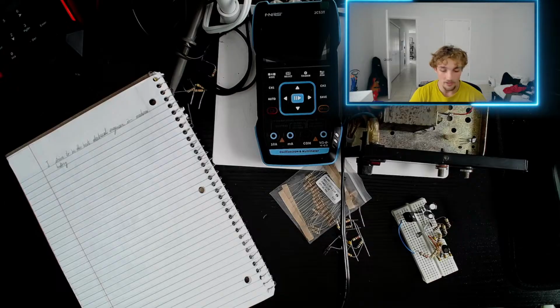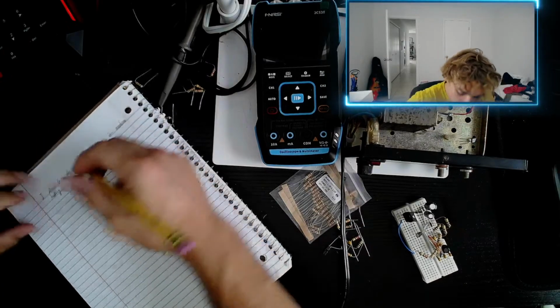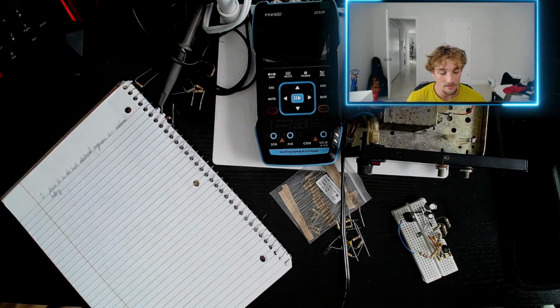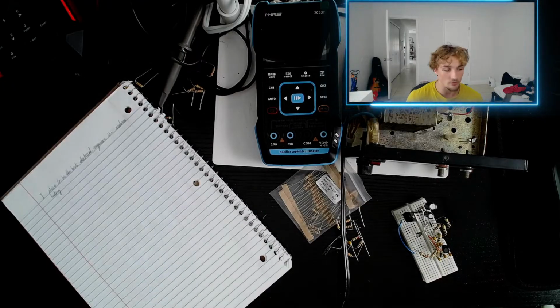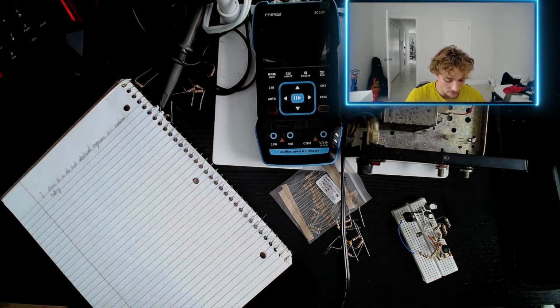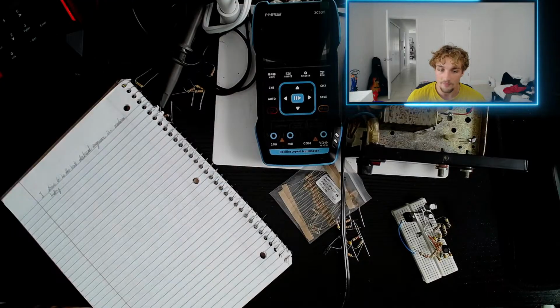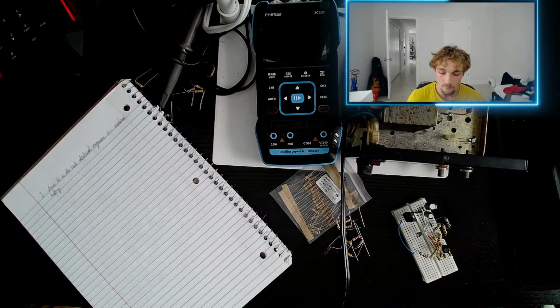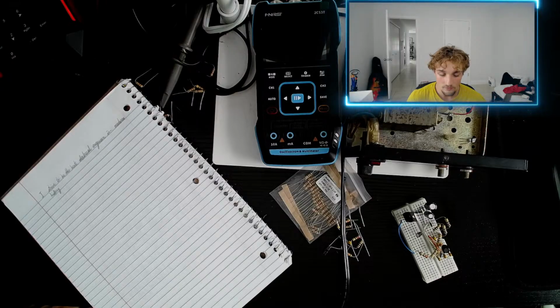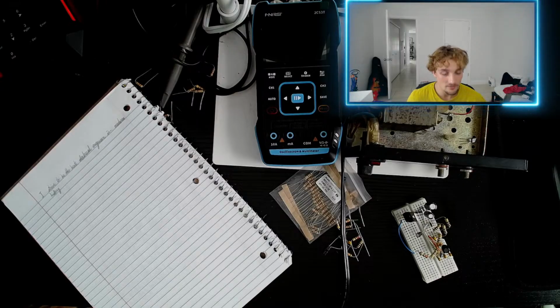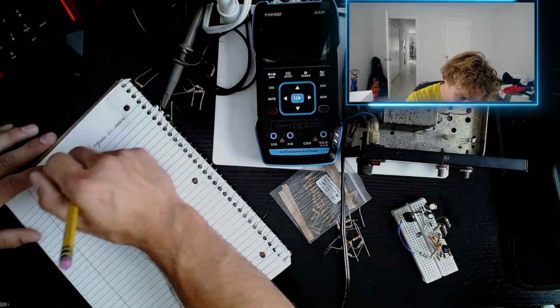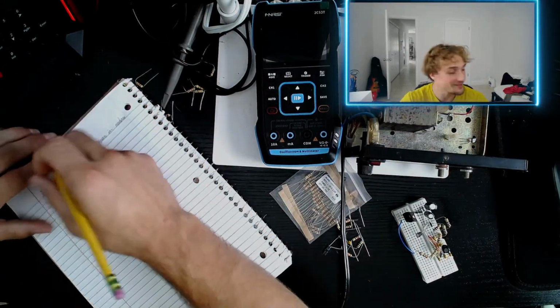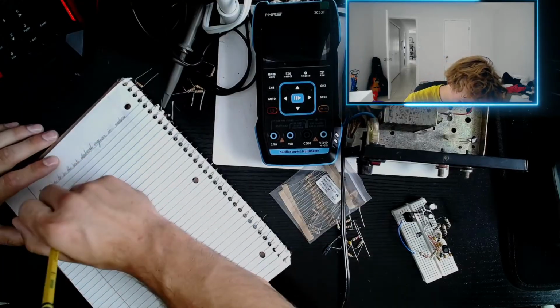So we're probably going to run approximately 2 milliamps of current through our collector, and therefore if we assume a gain of 100, we're going to have a base current of 0.02 milliamps, or what is that, 20 microamps? Let's see, let's write it down. I'm not sure. I can't think of the conversion right off the bat. I think that's correct, but let's see.